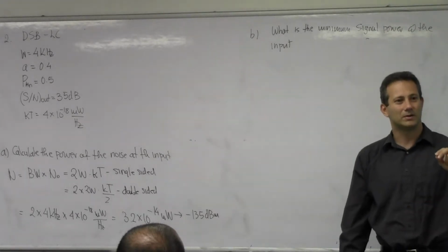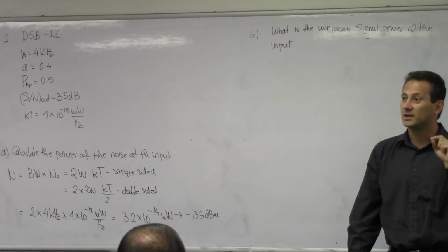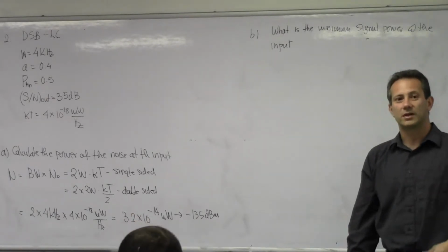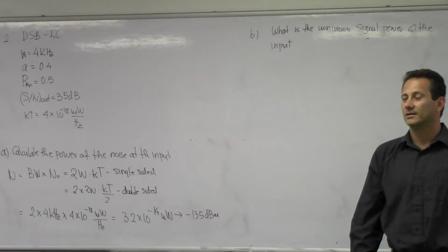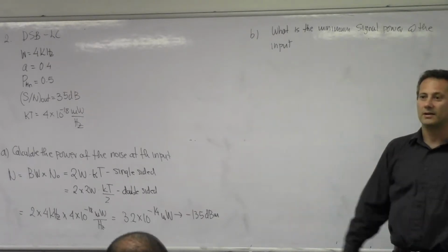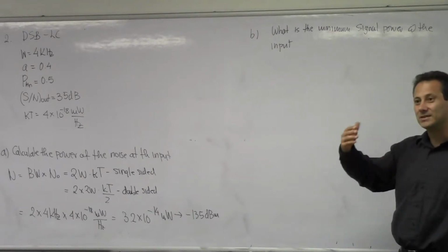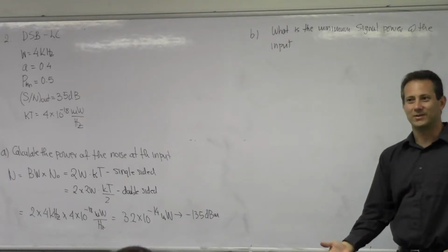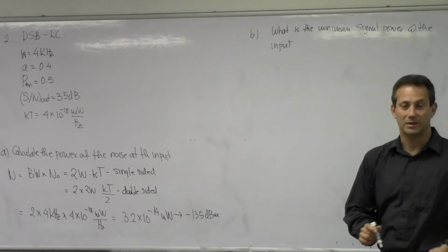The minimum signal power that you need to deliver to the receiver to meet its quality requirements is the receiver sensitivity. If this power is high, is it a sensitive receiver? No. The lower this value is, the more sensitive your receiver is. The smaller the power it requires, the more sensitive it is.